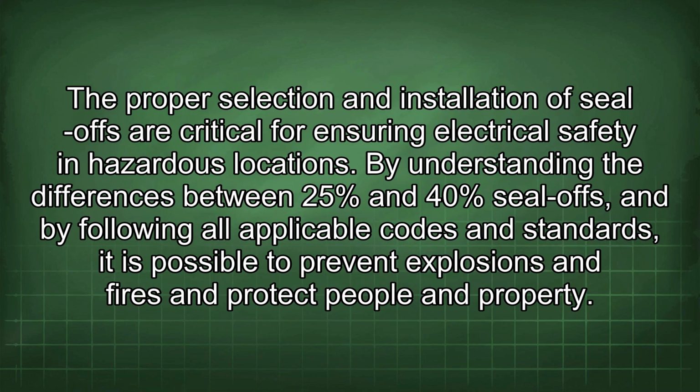The proper selection and installation of seal-offs are critical for ensuring electrical safety in hazardous locations. By understanding the differences between 25% and 40% seal-offs, and by following all applicable codes and standards, it is possible to prevent explosions and fires and protect people and property.